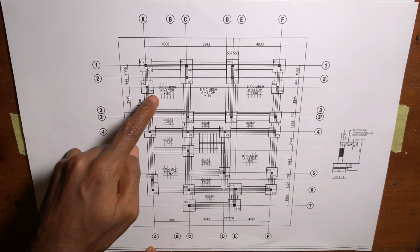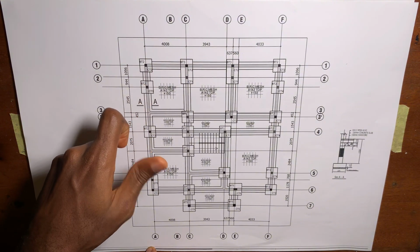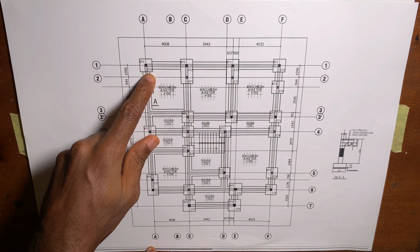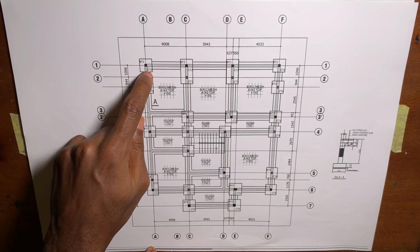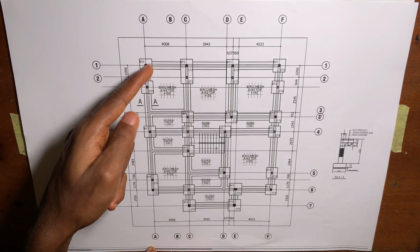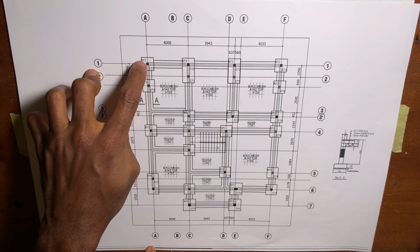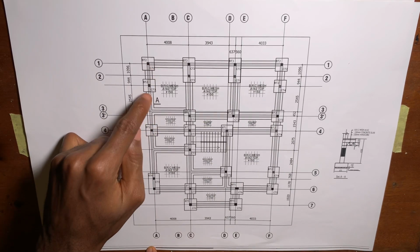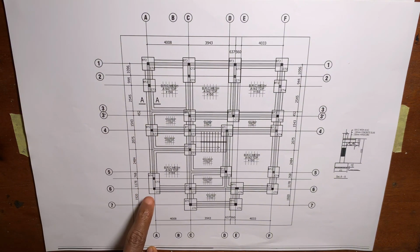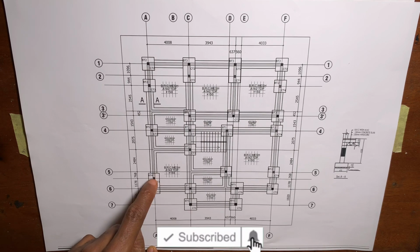On that same drawing, you can see there's another write-up showing CT2, CT3, CT4 and the like. This CT means the column type. As you can see, some parts of the drawing are thickened with black ink. The ink is thicker there, so that black ink shows the placement of your columns. In every column base, there will be at least one column. At BT2, there's one column here, another column here, another column here. For BT4, there are 2 columns, so it means that the column base is serving as a support for these 2 columns.